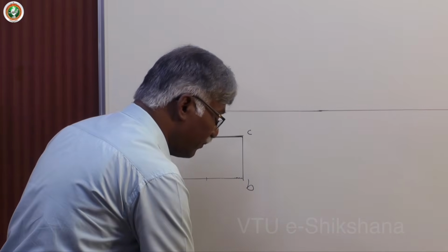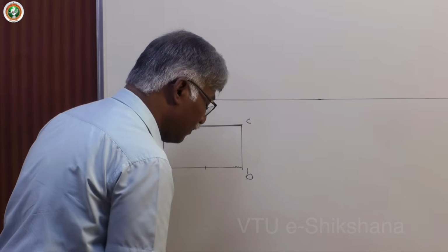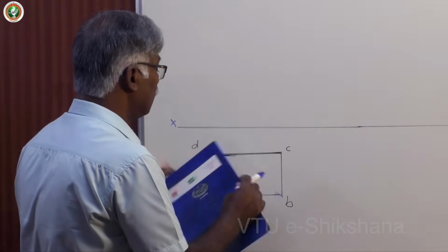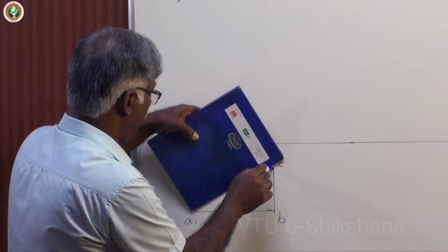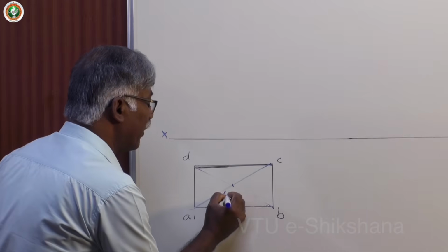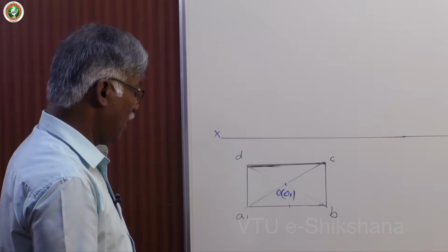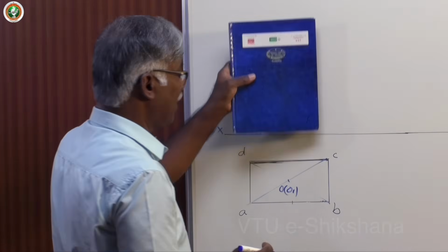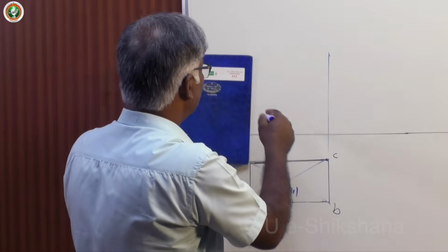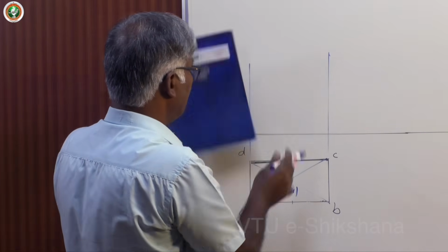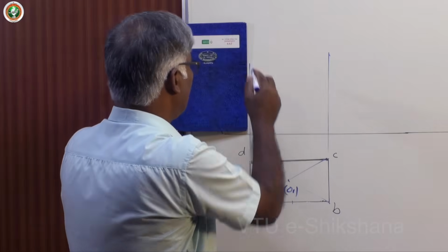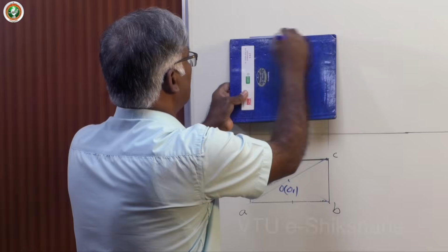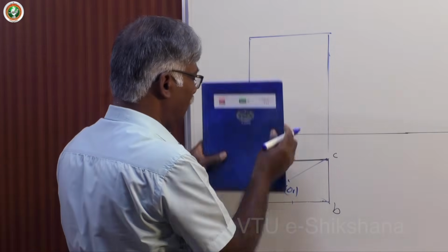Have the center of the top view with light lines. This is O1. You can also have A1, B1, C1, D1 in bracket, not necessary. Project this up. See that this is 60 mm, 65 height. Now project the axis also.